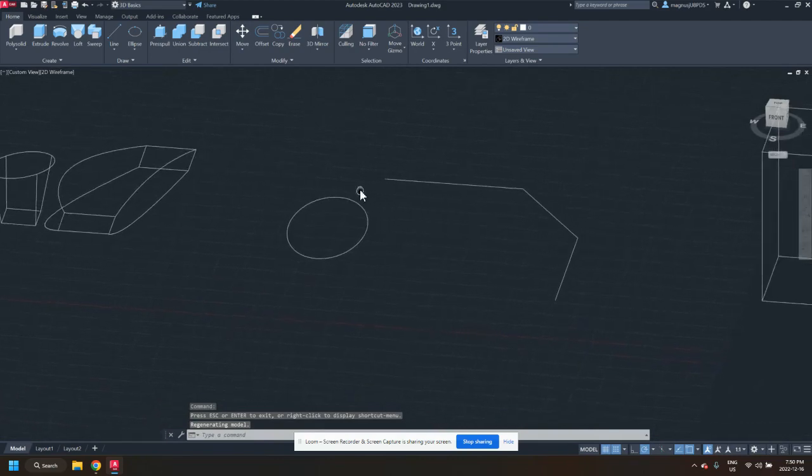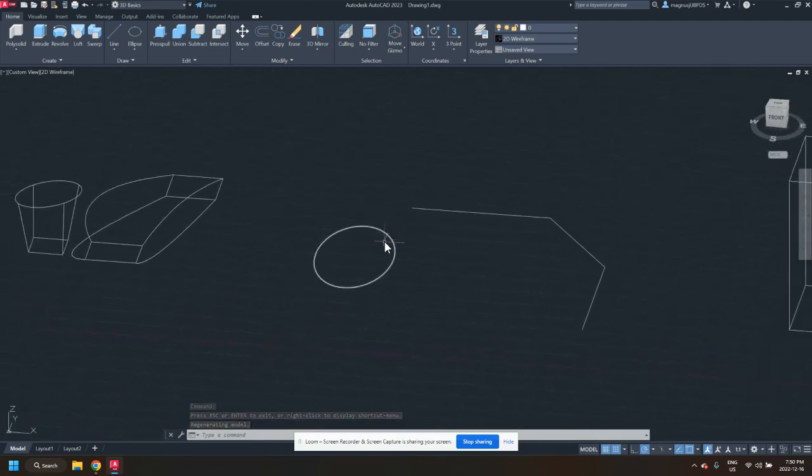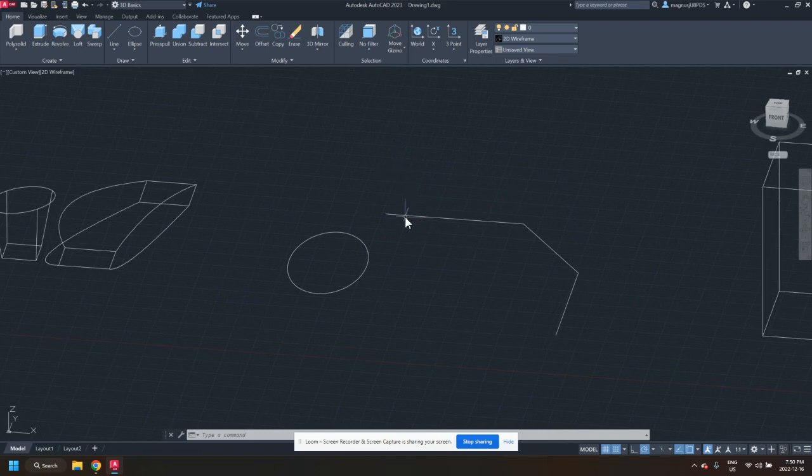The next function that we'll go over is the sweep. This takes a shape and puts it around an axis and goes along the axis. You'll have the shape, and you'll also have a line that you want to be the center axis. Let's say we wanted to make a tube that goes straight for a while, goes this way, and then goes down.